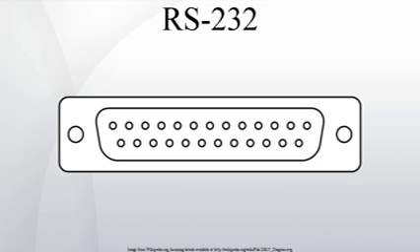On an external modem, the status of the ring indicator pin is often coupled to the AA, auto answer, light, which flashes if the RI signal has detected a ring. The asserted RI signal follows the ringing pattern closely, which can permit software to detect distinctive ring patterns. The ring indicator signal is used by some older uninterruptible power supplies, UPSs, to signal a power failure state to the computer. Certain personal computers can be configured for wake on ring, allowing a computer that is suspended to answer a phone call.